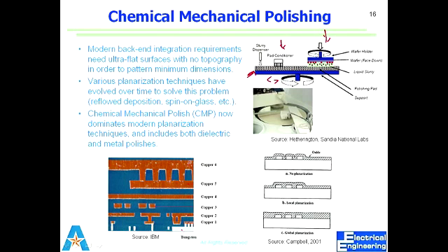So slurry has things that chemically wet or has grains, which basically rub the surface to remove the material that you want. So it's a very well-controlled process, but a very dirty process, because slurry is a dirty liquid, and then what comes off of the wafer is also contamination. But CMP is what we do after every level of devices.